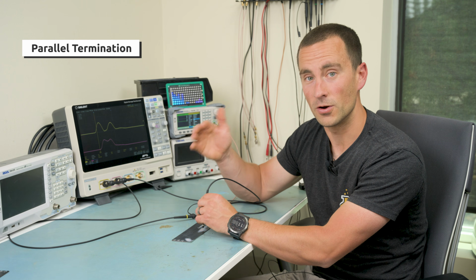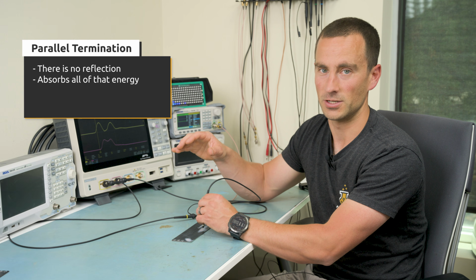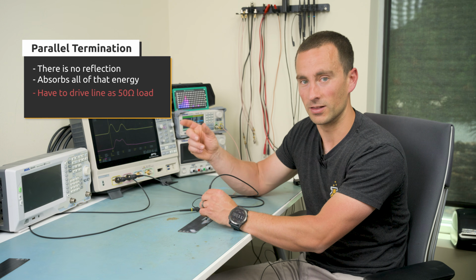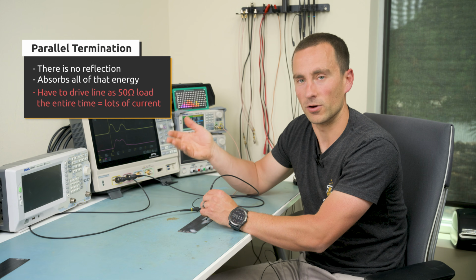With parallel termination, you don't get this because there is no reflection. The parallel termination absorbs all of that energy. The big downside is that you have to drive the line as if it's a 50 ohm line the entire time. So it takes a lot more current to do.